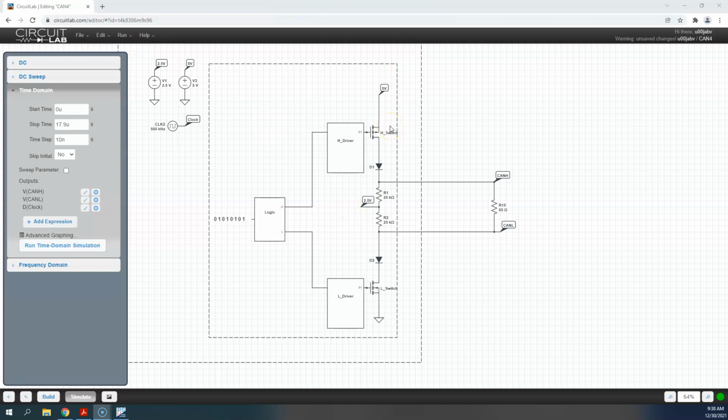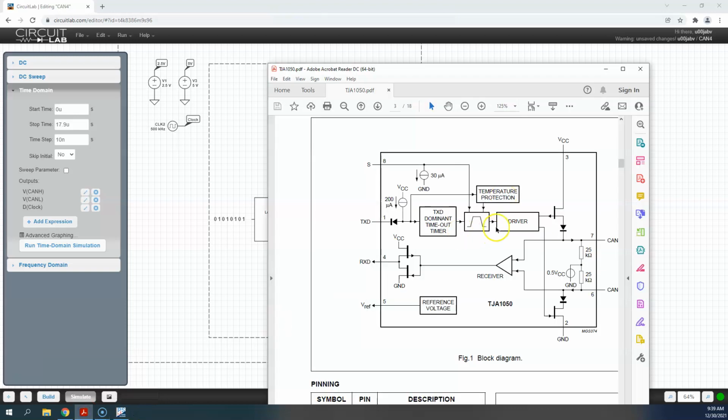I've also replaced the physical, time controlled switches with a field effect transistor, a MOSFET. So these are a high side driver. This is a transistor which acts very quickly. It acts the same as a switch. The schematic symbol of it, you could think of in your mind as just being a switch that is either open or closed. So it's one that acts very quickly. We have this driver chip which controls those high side and low side drivers.